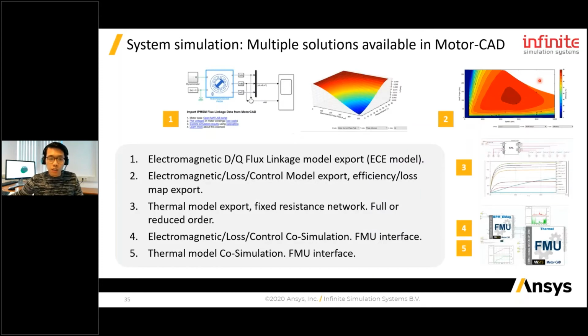So the system simulation in Motor CAD, you do not have the system simulation. The system simulation is more for you to export this functional mockup into Twin Builder or into Simulink for system simulation. But of course, even though there's no real system simulation in Motor CAD, there is indeed the efficiency map and also the drive cycle, which is also an important factor for you to consider as a system engineer.